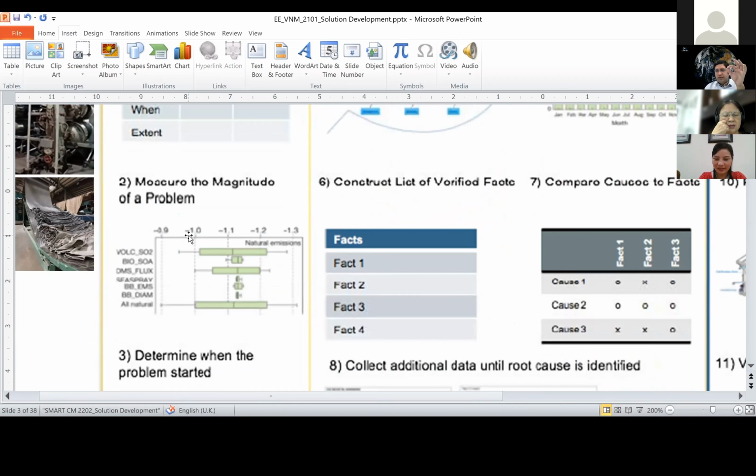So there is a method called an orifice method. If you estimate the size of the leakage and the length of the plume, then you can estimate the quantity of steam flow through it. But there are other methods. For example, if you go to Engineering Toolbox, you might find another graph which tells you how many bar of pressure and what size of orifice would give you how much quantity of the flow.